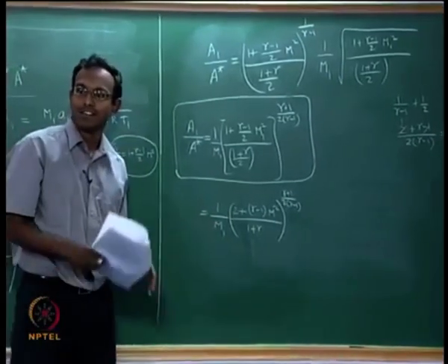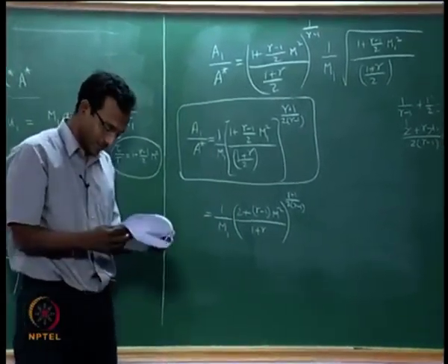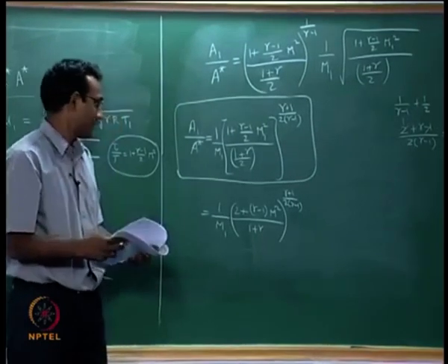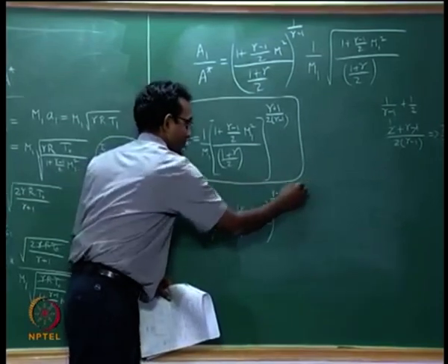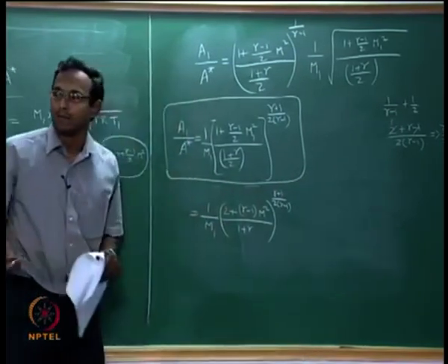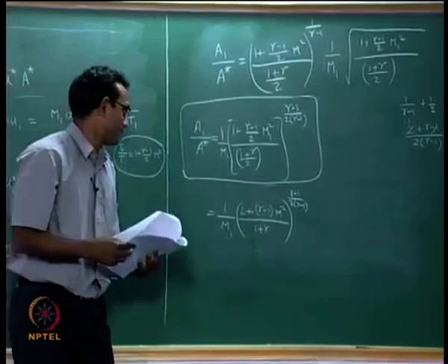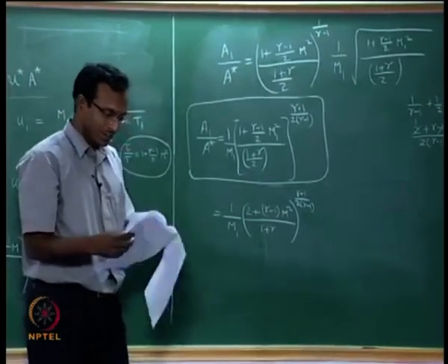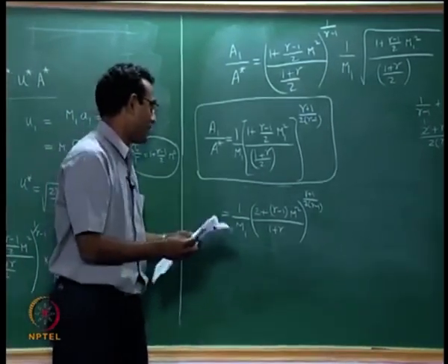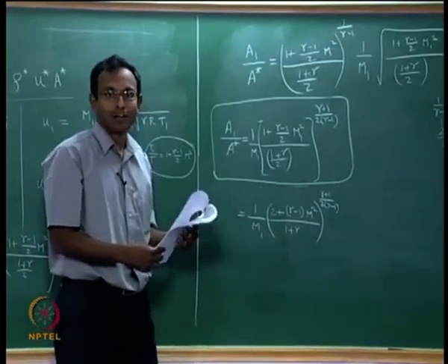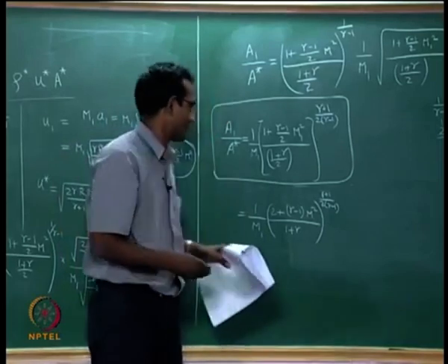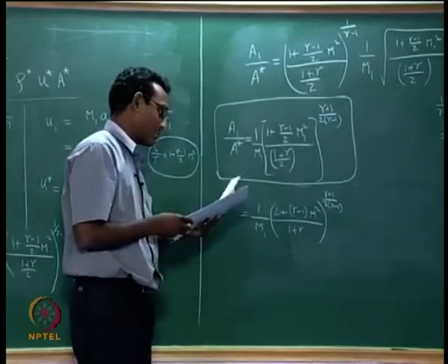This is probably easier if you are doing your own coding for this function. Or I will take this divided by 2 as a square root for this whole thing. That is another way people write it. Whichever form you remember is good for us. This is called the area Mach number relationship, very useful in calculating Mach numbers at different points in your duct.